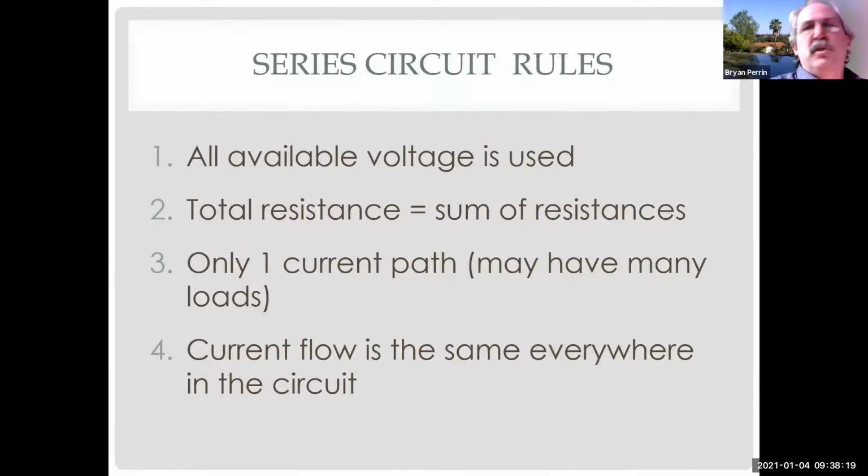So if I have a starter, for example, my starter needs to use what? All the voltage, less whatever's used by the cables and connections. If it's not using all of it, that would mean maybe my starter has a bad connection somewhere. So maybe I have a corroded battery cable that has a lot of resistance. So now, instead of my starter getting 12 volts, maybe the battery cable is using 5 volts and my starter only gets 7. Or we've actually seen where the battery cable gets 11 volts and the starter gets 1 and doesn't work because the battery cable's bad.